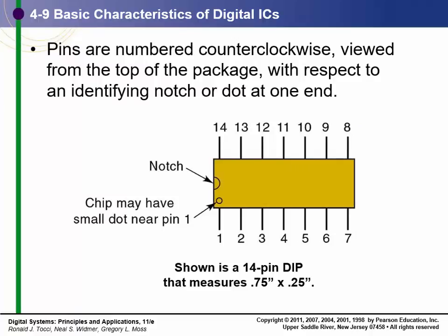The pins are numbered, and I'm going through this even though we're not going to do it in the labs in this particular class, because this plays into all your labs. If you look at analog parts, they follow the same notation. This is a standard numbering package for all electronic chips, ICs, whether digital or analog. So if you're talking about an LM741 or an LM7805, which are linear chips, they follow the same package.